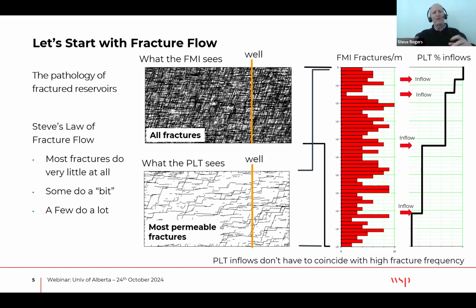We can do some shear tests and get some joint strength properties, but the easiest way to understand how fractures have different properties is actually to think of them hydraulically, because hydraulically we can pump fluid through a fracture network all day and we'll actually understand something about how conductivity or apertures might change, in a way that is much harder to do mechanically.